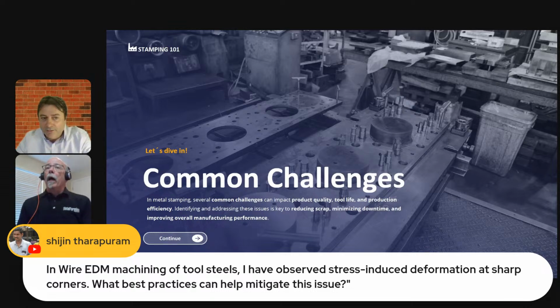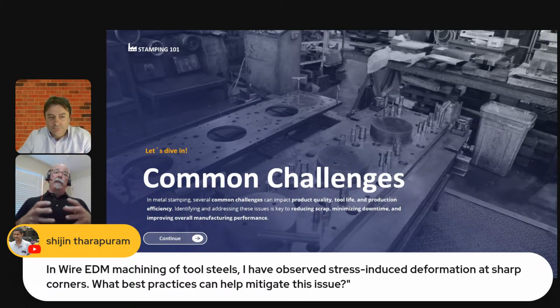can talk about it. One of the things that happens with wire EDM is that, think about how you've got a hardened piece of tool steel. So it's hardened, it's tempered, and now we're going in there and we're going in with a wire. We are sending a high electrical charge in there that is basically doing what? We say it's cutting, we're wire cutting, but it's not a little saw blade that's going in there. It's very, very high heat that is basically evaporating the material as you're cutting it.